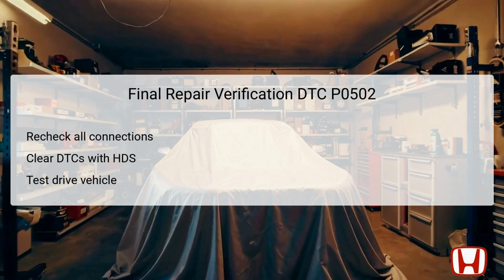Start by rechecking all electrical connections related to the CVT speed sensor and any pertinent wiring that may have been repaired or replaced. After confirming that everything appears secure, use the Honda Diagnostic System, HDS, to clear all DTCs from the PCM's memory. Finally, it's vital to perform a test drive of the vehicle to verify that it operates without re-triggering the DTC P0502. Observing the vehicle's performance post-repair is essential in confirming that the troubleshooting process was successful.